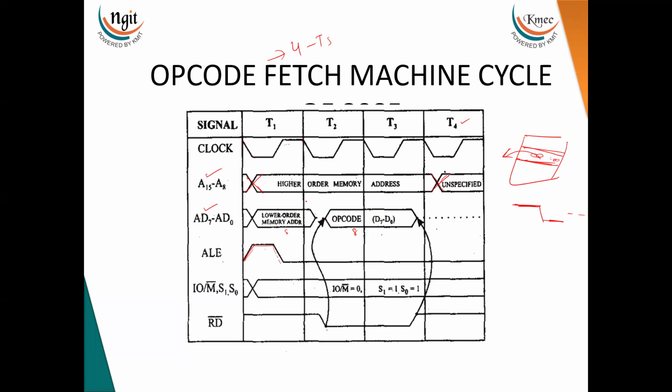If we are trying to represent more than one signal, we represent them like this, with the box type indication. Inside we write whatever the data is. Representing all the signals individually, 8 bits, 3 bits, is very difficult. That's why we represent all the bits, all the signals together. Now this is about the read signal. Read is applied and, up to the third clock cycle, the read will be enabled and the data will be placed on the data bus.